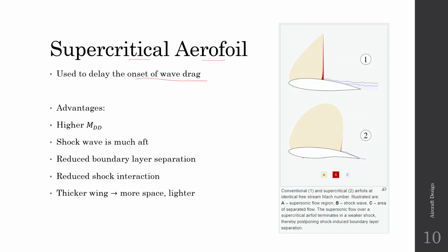The main method is that if we keep the leading edge very thick and very rounded, then the flow accelerates very fast over this section. If instead we make this section flatter and camber this section more, then we can get the same kind of lift, but the flow will not accelerate so fast.